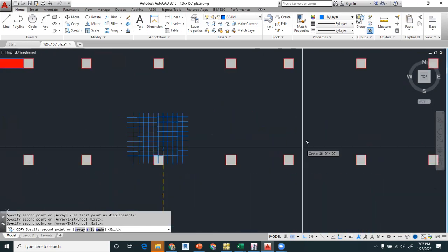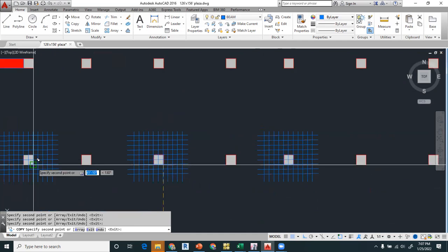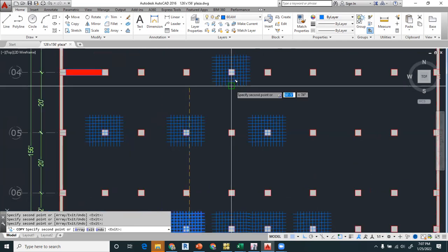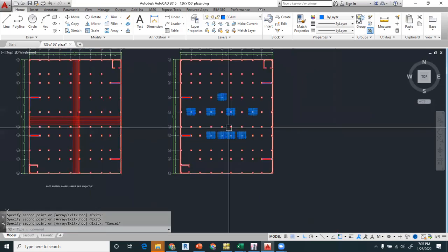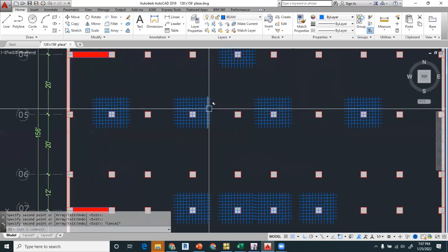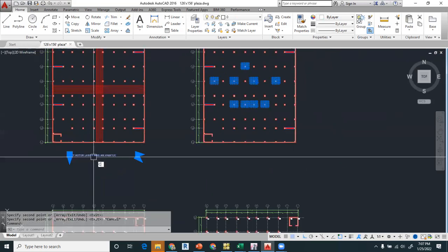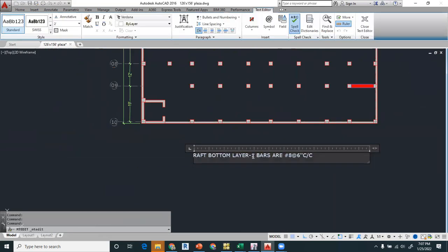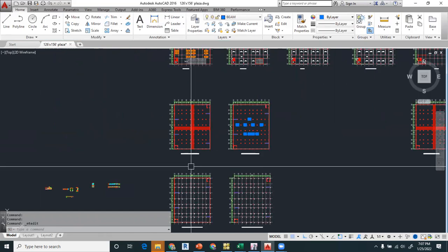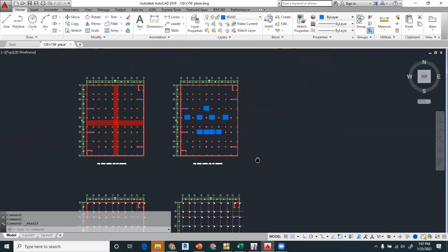You will put that reinforcement on all those columns where the second layer was required. So this is just for the reference to how you provide it, right? This will represent the second layer of the reinforcement, and you will write, for example, this is first layer and this is second layer, and he will confirm these layer spacings from the section you will cut from the raft. So this is the second layer and this is the first layer.